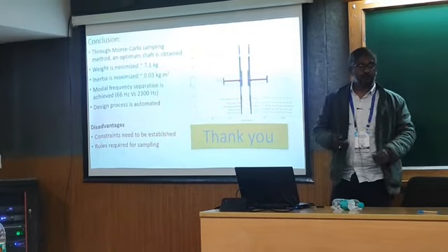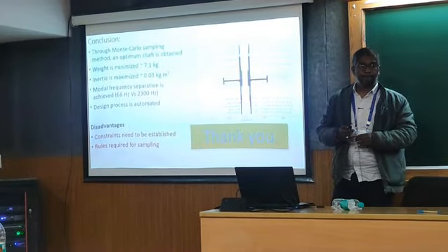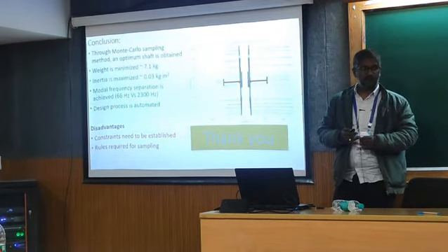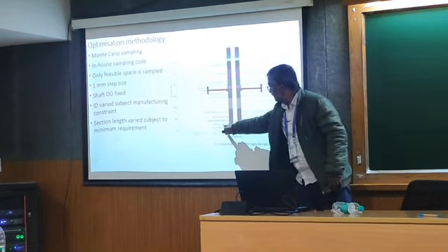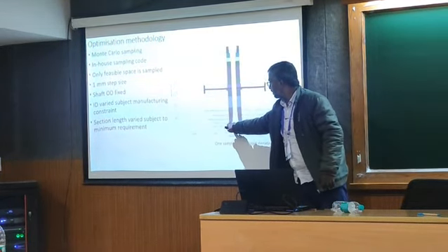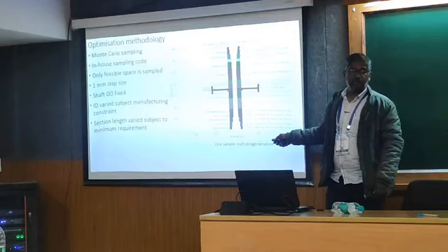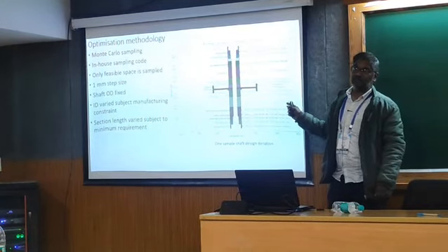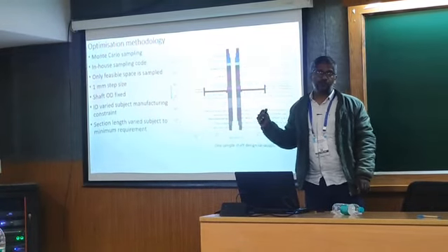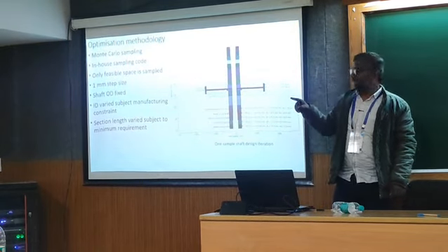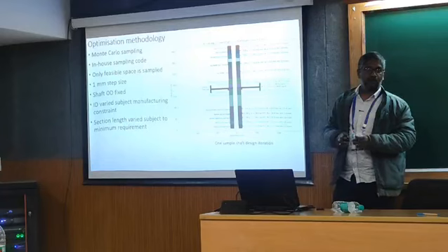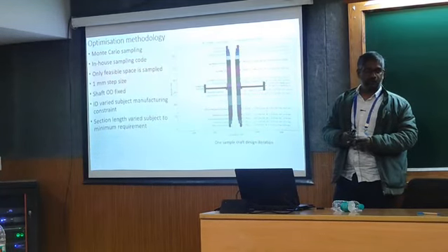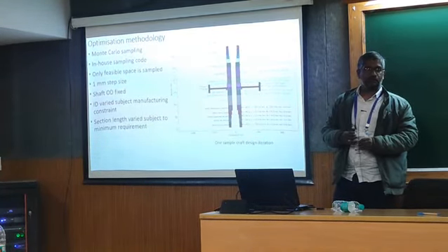AMBs also use auxiliary bearings. Is there any need for auxiliary bearing? Yes, that is there. We have this section, bottom aux bearing. This is the region where auxiliary bearing comes. In our current test rig, we are using a phosphor bronze bush in that area. Actual rig that is going to get higher RPM will be having rolling element bearings. Right now it is a bush.